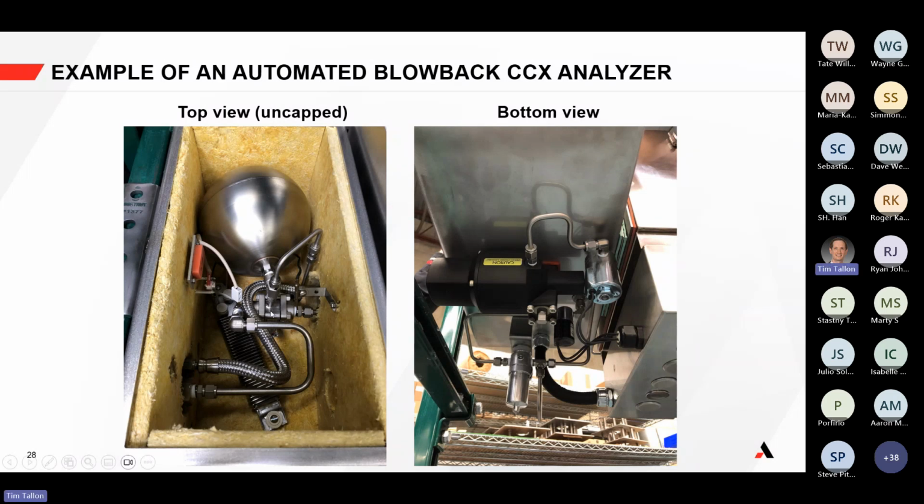So here's the three-way valve, the high pressure air. Again, it's heated so that nothing can condense within the line. The hot air can vaporize any water condensation that may accumulate, or prevent any accumulation of condensation because of cold air. We don't want high pressure cold air. So as you have high pressure heated air, the three-way valve lets it go through the hook, out through the process and out through the filter.